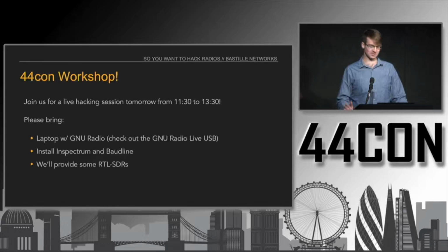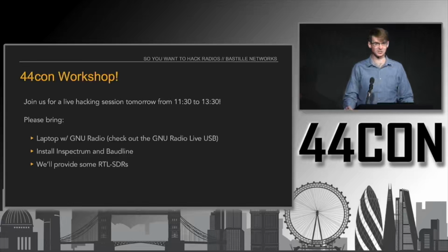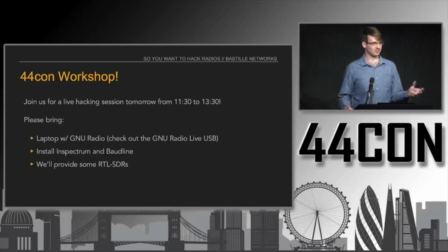So if you want to participate, please show up with a laptop with GNU Radio. If you don't want to go through the super fun process of installing it from source, you can grab the GNU Radio live USB image and flash it to a USB stick. And that has all the tools that you'll need, kind of canned and pre-installed on it. Additionally, it would be great if you could install Inspectrum and Baudline, which are 2 open source tools that are really awesome. And then we'll provide a whole bunch of RTL SDRs, which are really cheap, inexpensive software-defined radios. So if you bring your laptop, we'll bring the radios, and we'll have a party.